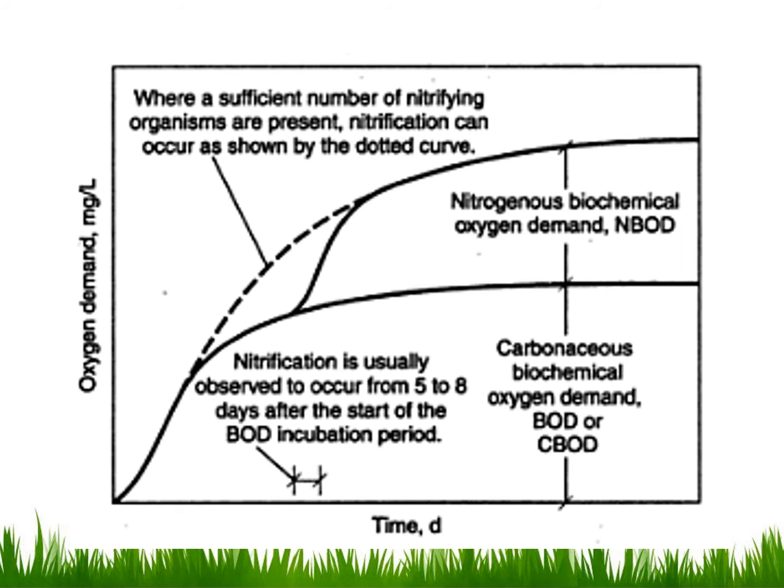However, carbonaceous BOD is also continuous because we have only consumed about 60 to 70% of it in the first 5 days. We were only interested to get the rate, and now it will be depleting the carbonaceous organic content to 95 to 99% in 20 days. And meanwhile, at the same time, the nitrogenous BOD is also active.